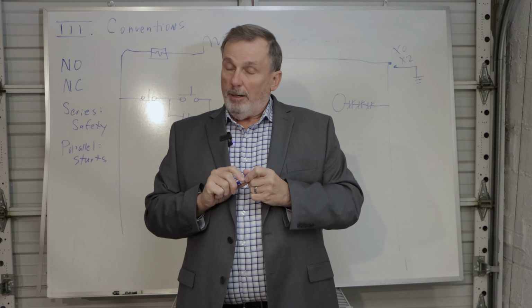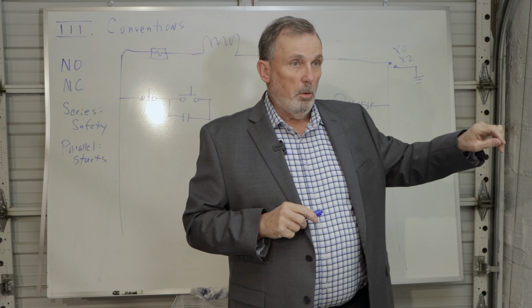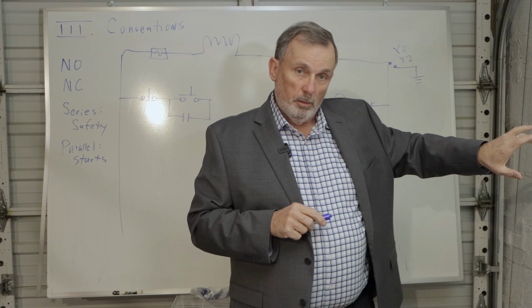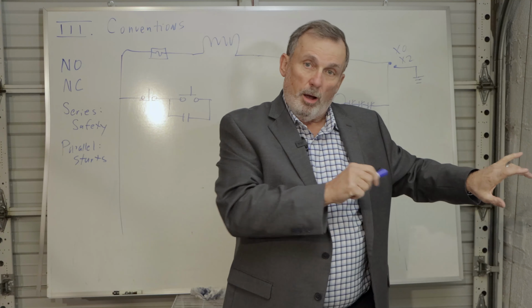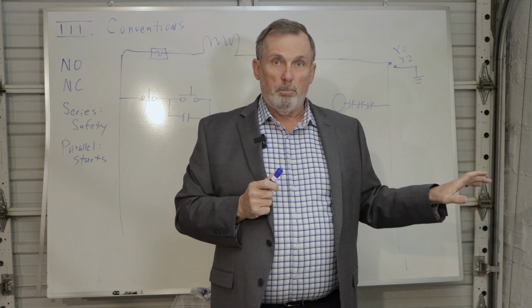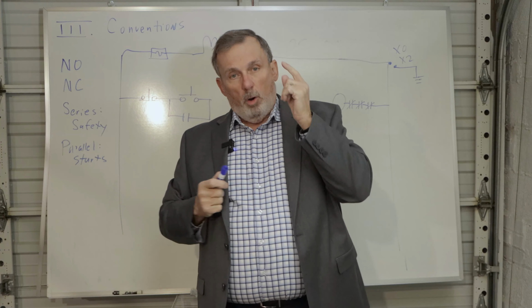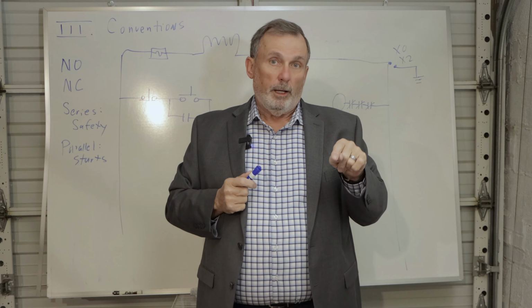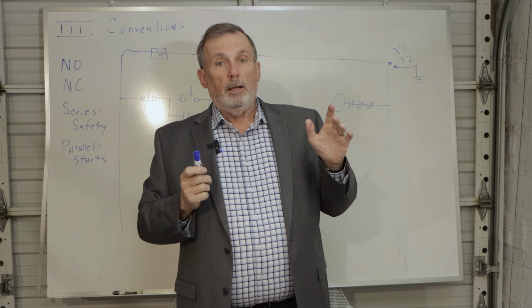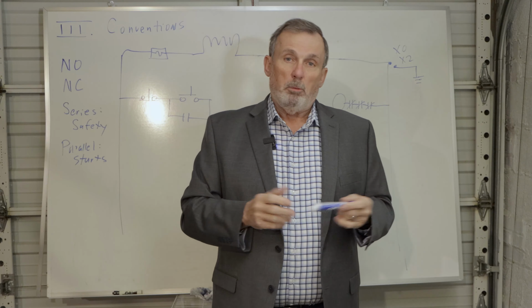And a lot of times, the button that starts the motor starts a motor remote from the start button and the light shows up in a control room, also remote from the starter and from the start button. So we want to know wherever the control room is that the motor is running or that it's not running, and we want to have this indication be relatively reliable.